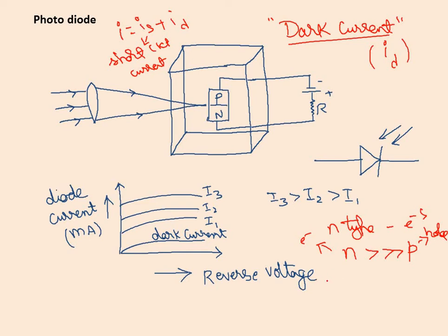Now at that particular instant of time, I am calling it n dash equal to n plus delta n, the change in that, because this is the initial number, this is the increment, and that was the total after light incident. Similarly, p dash I can write as p plus delta p. Can I write it down or not? And remember that delta n will always be equal to delta p, an equivalent number. When an electron jumps out, it subsequently gives us the hole. So delta n and delta p will always be equal.